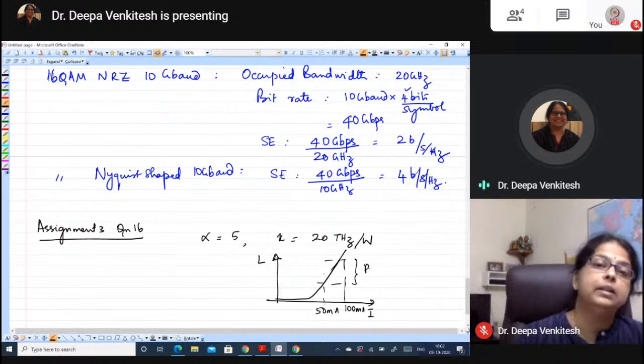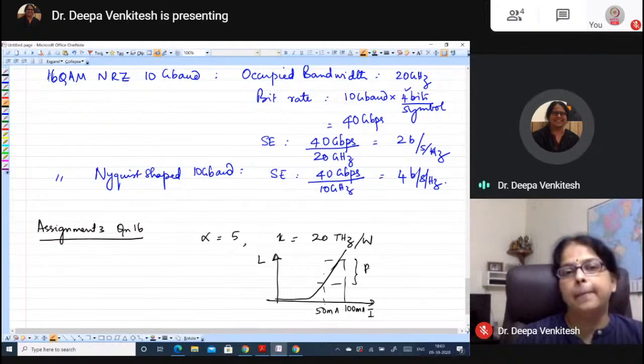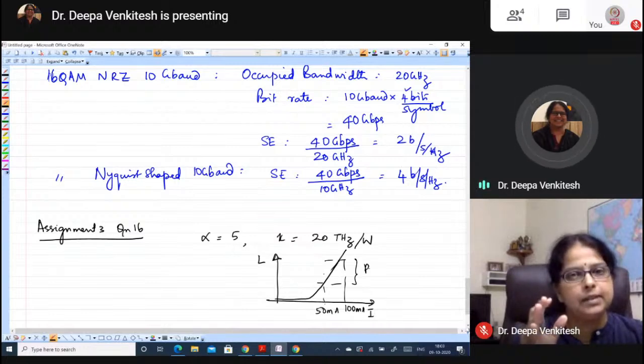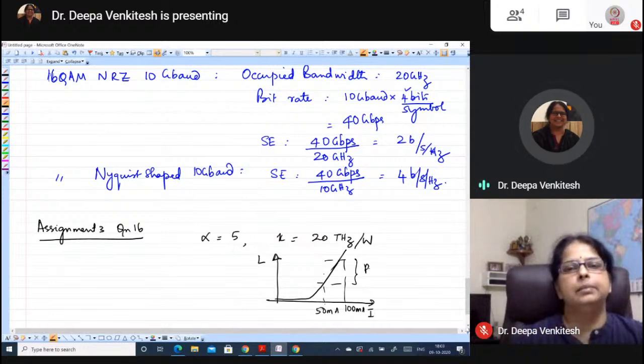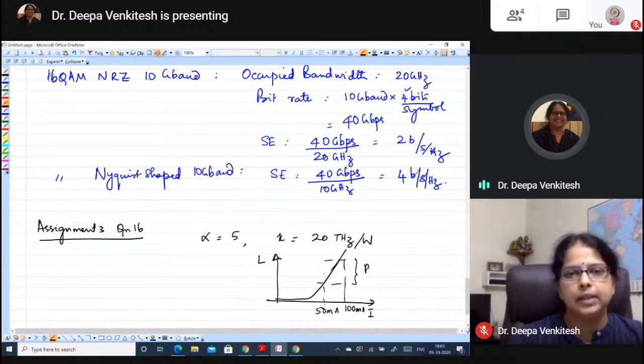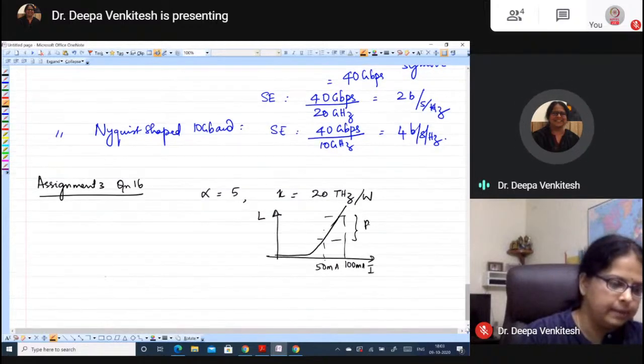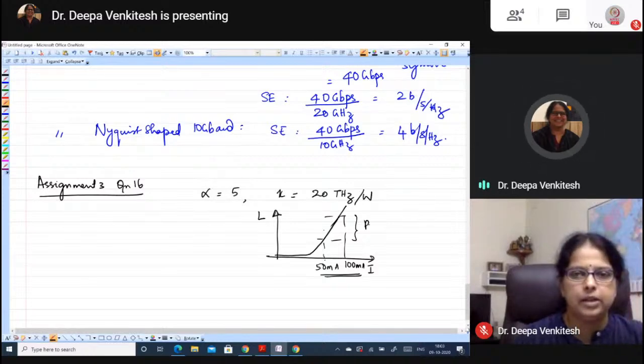In the videos, we learned why the center wavelength is shifting as you change the current, because as you change the current, the carrier density changes. Carrier density changes, the refractive index changes. And the refractive index changes, the wavelengths that are supported by the Fabry-Pérot cavity change, and that's how you start getting a chirp.